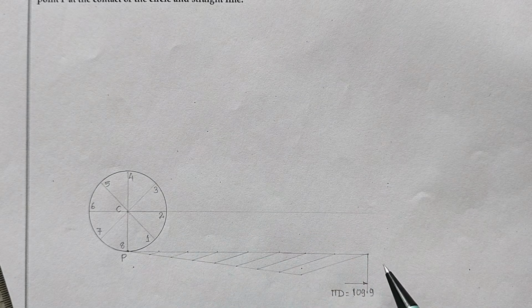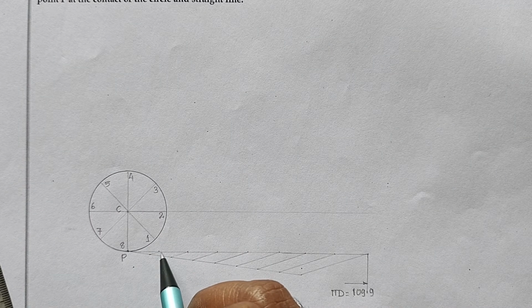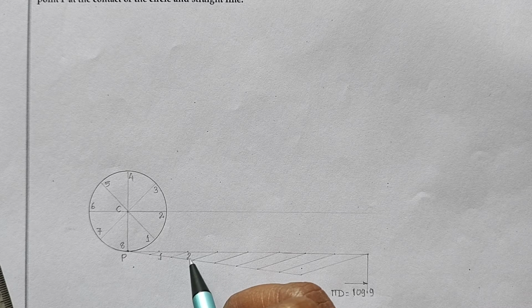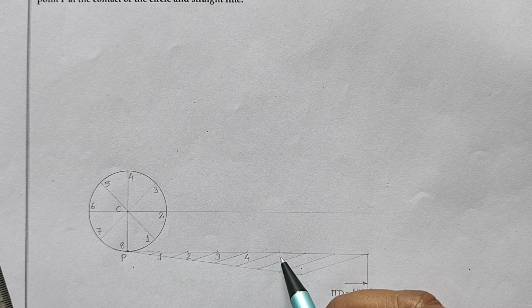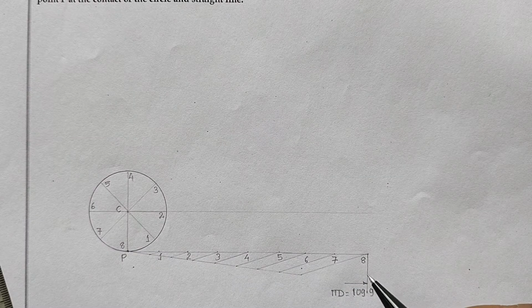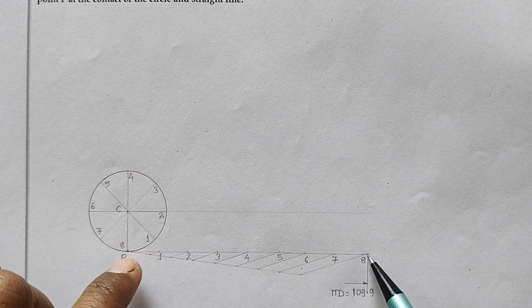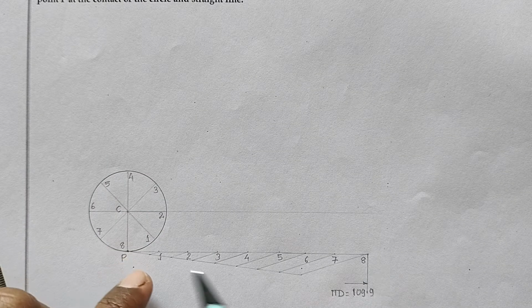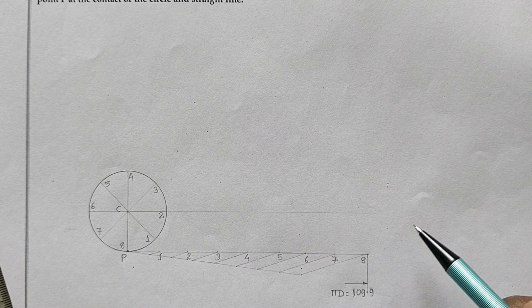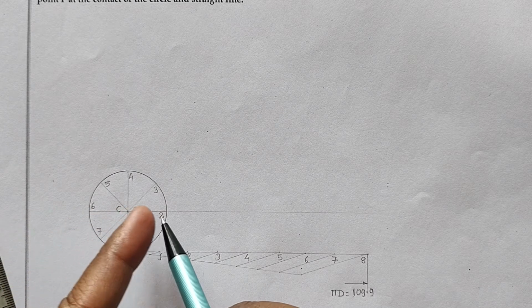So on this circumference also I will mark the numbers. Where this rolling circle first touches this point, this is 1, then 2, then 3, 4, 5, 6, 7 and last 8. So when it rolls 8 divisions, ultimately it will cover 8 circumferential divisions on the straight line. Now when it rolls one division, this one point will align with this one point, that means 1 will match, so the center will shift to this side.